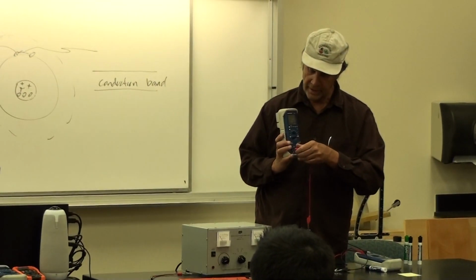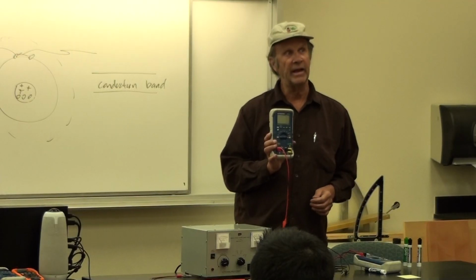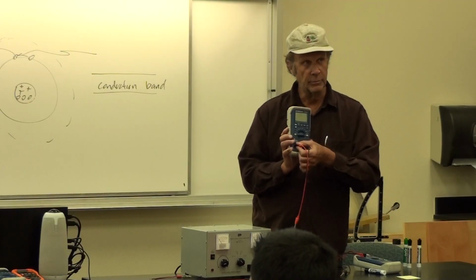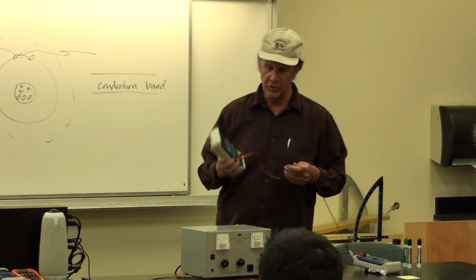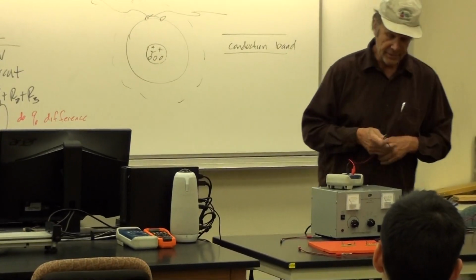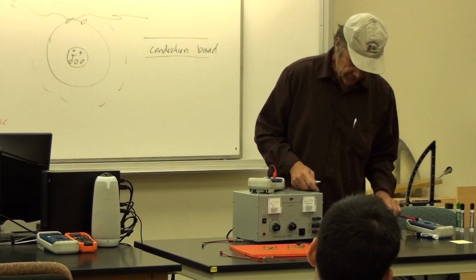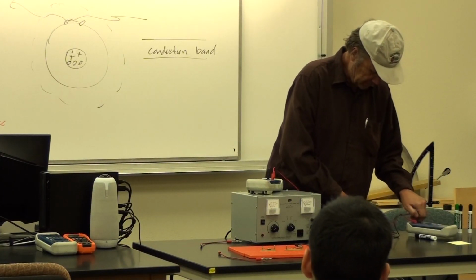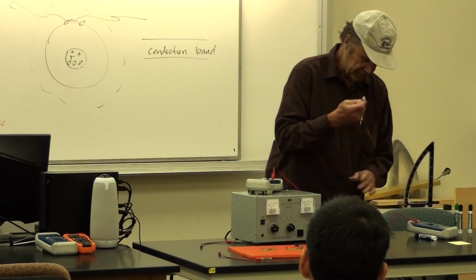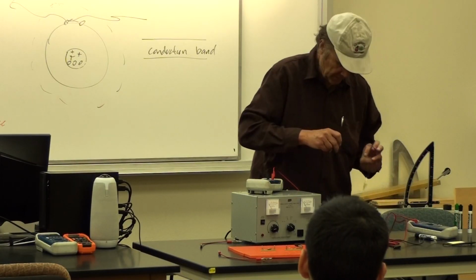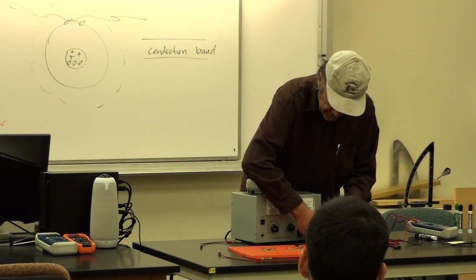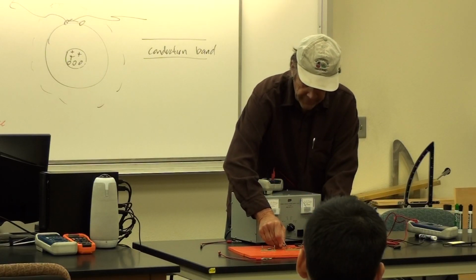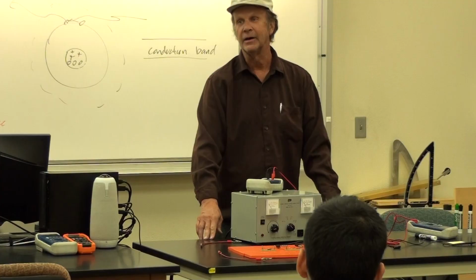But you don't want to go all the way across like this unless you're measuring amperes. We're measuring milliamps, so it's going to be way more accurate to go with these two in the middle. No matter how many times I say this, there are some people whose knee-jerk reaction is to do the wrong thing, and this will blow the circuit. If we blow the circuit, it's not a huge deal, but it's going to put Mark to work replacing fuses when we would rather have Mark out here helping us, right?